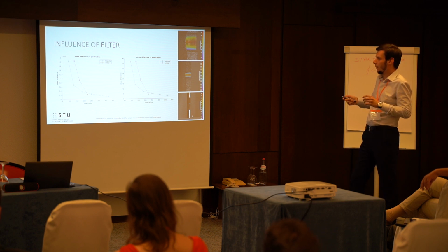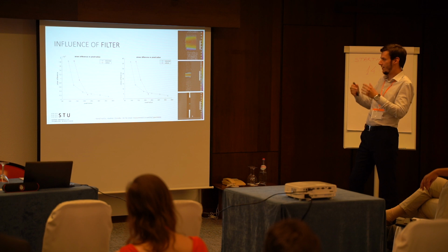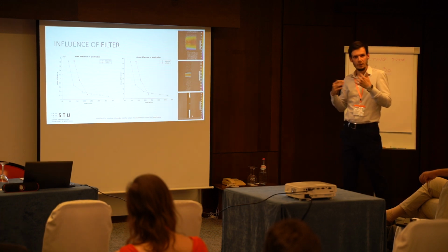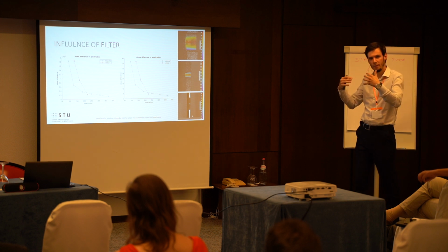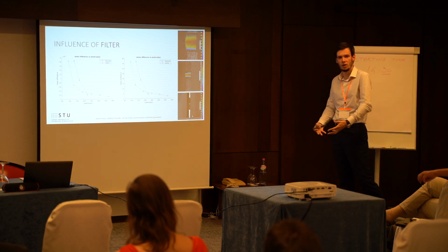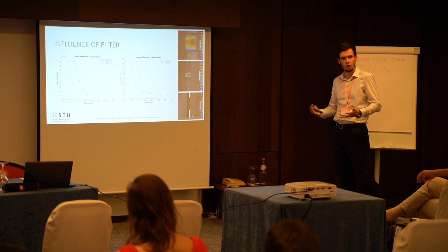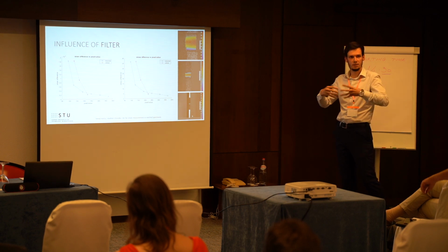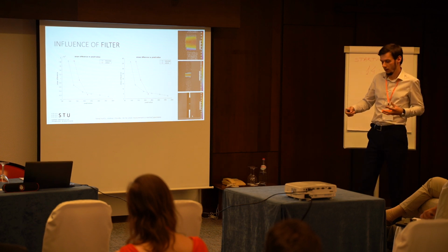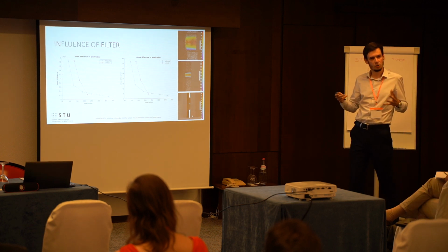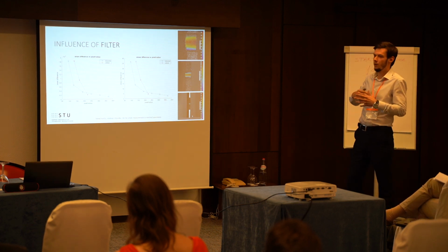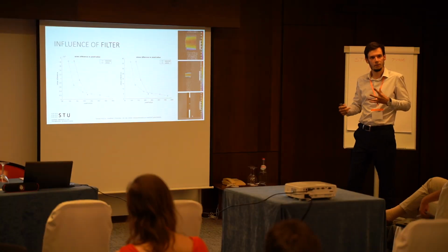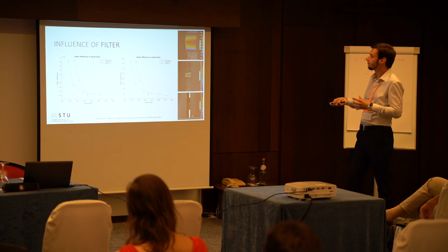And the thing is that if we have in real life a larger or smaller notch, it doesn't really matter, because we can change the measurement equipment. For example, we can change the camera for cameras with larger resolution, or we can change the optical system lens. We can use a microscopic lens, so the measurement equipment could be utilized for practically any size of the notch.